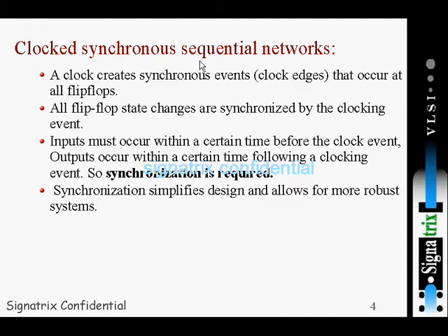Clocked synchronous sequential circuit: a clock creates synchronous events that occur at all the flip-flops. So we know that in our design, suppose we are saying that our design is synchronous. Synchronous means there is one global signal, so all the events will occur with respect to the clock. Suppose you take an example: there are 10 flip-flops, and the common source is the clock to all these flip-flops. So whenever the clock comes, they will sample the input to the output. That is the objective of the flip-flops.